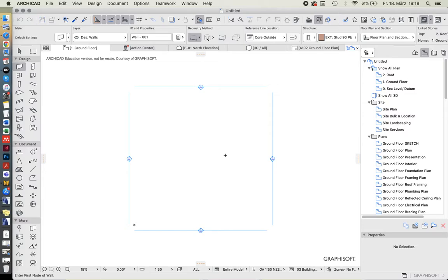Once you get a bit more comfortable with the software in general and you know your way around, I highly recommend setting up not necessarily a template, but a master file. So having one file, you can call it the ArchiCAD 23 master file, save it somewhere on your desktop. So whenever you do start a new project, you don't just start from scratch, but you can work with that master file. And in there, it's really good to set up the tools and settings and layers the way that you like them to be. And you might even be able to copy in a few elements and symbols and small drawings like furniture and these sort of things that you like to work with. And you can copy them into that document so you have easy access to these elements all the time.